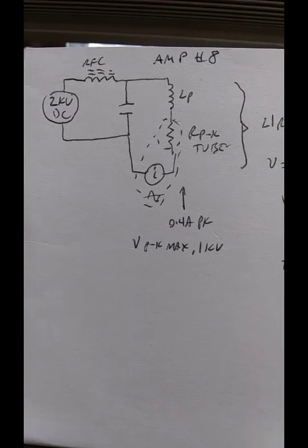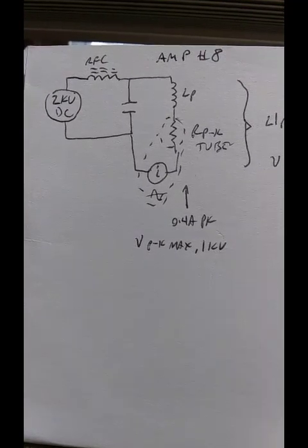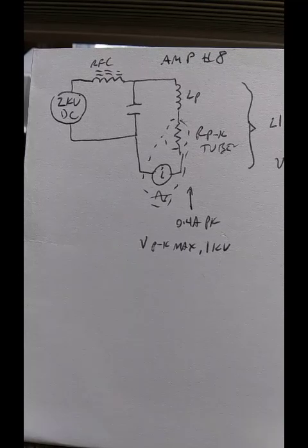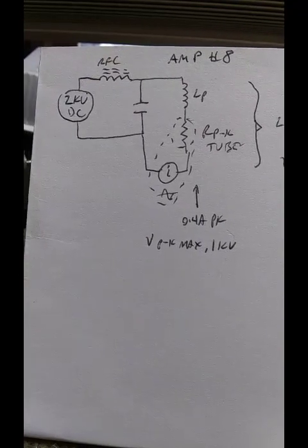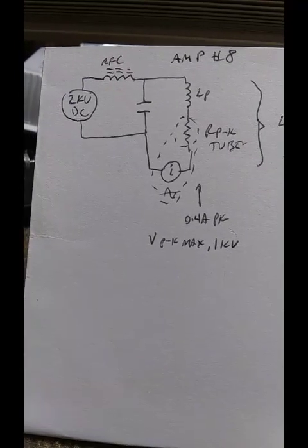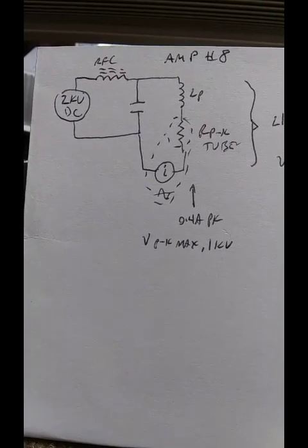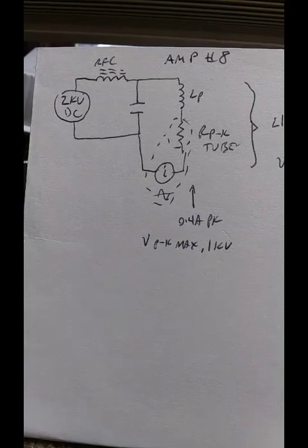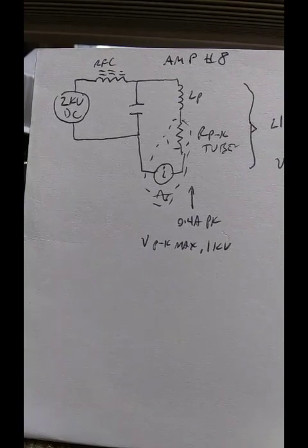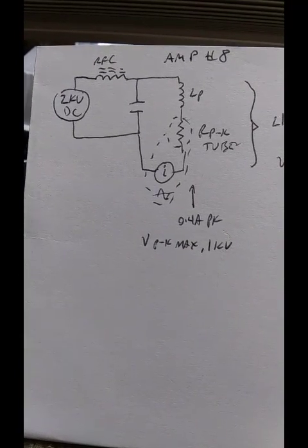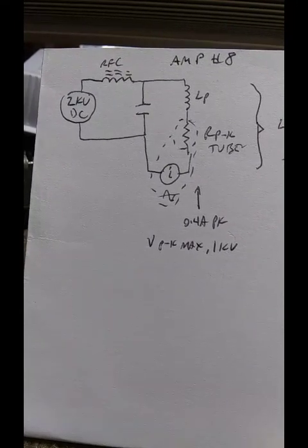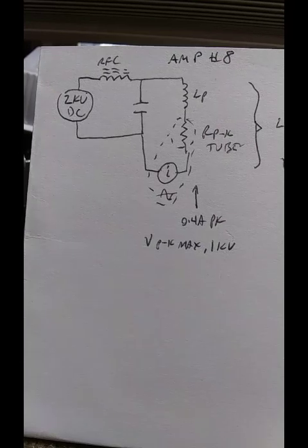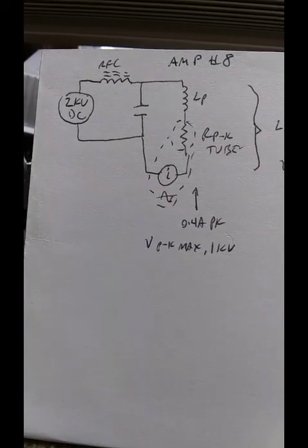That plate inductor, as I've shown already, is the component that establishes the voltage drop across the plate. If it's extremely high value, there won't be any voltage swing and no amplification. None of the books I've ever seen or papers show how to calculate that value, and hams universally guess at it. After that, they're forced to vary drive levels and vary voltages and vary tuning to try to guess at proper operating conditions, and their amplifiers are usually badly distorted.